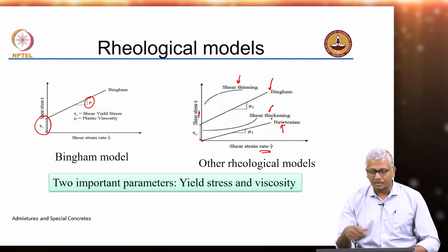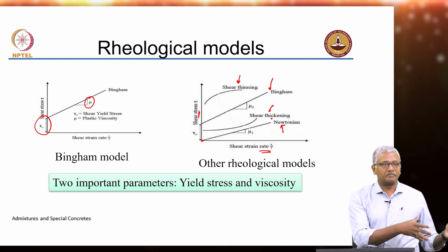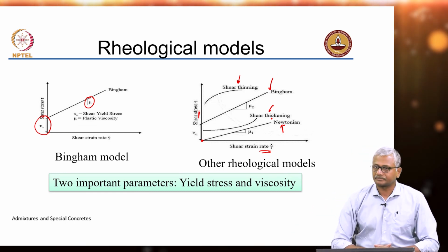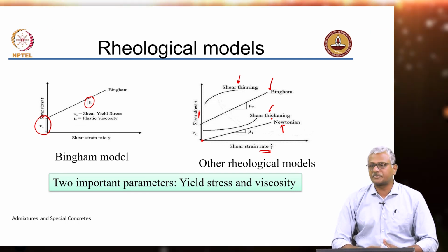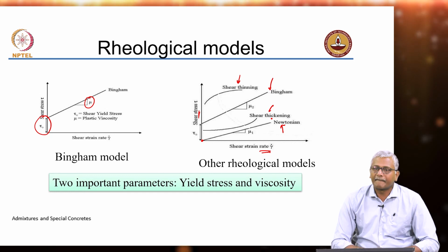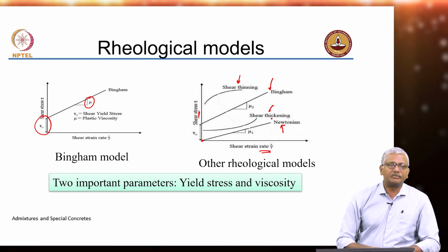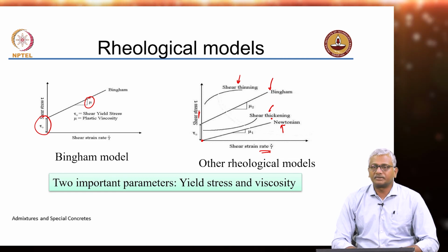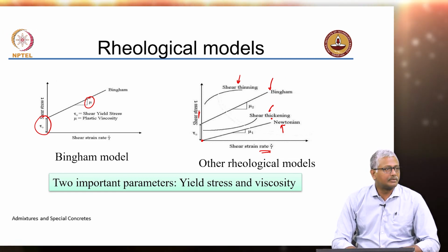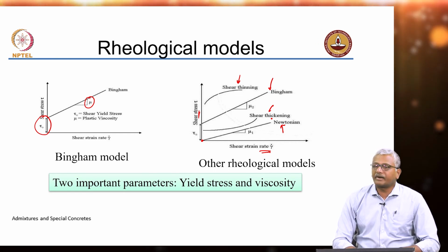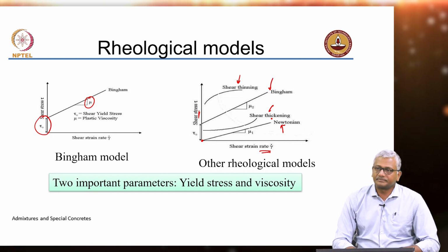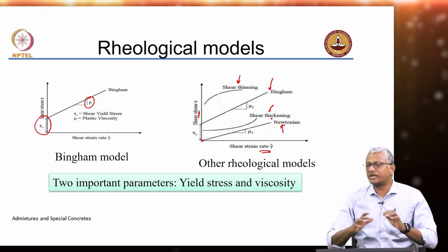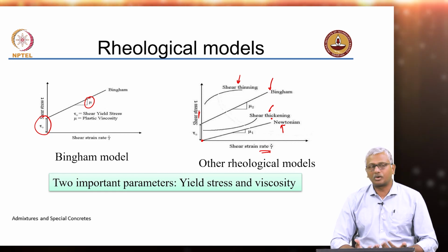So, let us look at a practical scenario. Let us look at a scenario where concrete is mixed at the ready mix plant and then it is getting transported. It needs to be dumped into the formwork at the job site. Okay. So, what kind of behavior do we expect from concrete? What kind of behavior do we want? When we are slowly agitating it in the truck, is that a high shear or a low shear? Low, right? It's a low shear. When we are trying to pump it, is that a high shear or low shear? We are increasing the shear rate when we try to pump it. When the system comes into the formwork and is trying to come to rest, shear is low or almost 0.